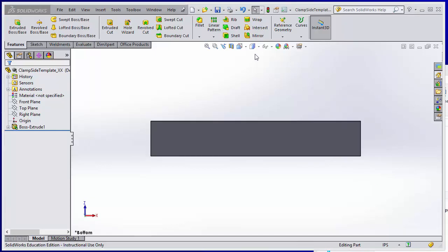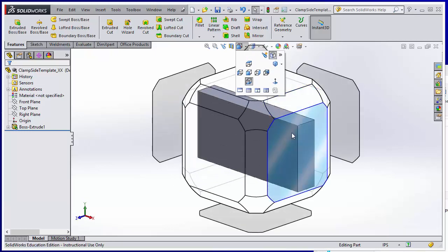You should note that it only works as the bottom if you designed on the front plane. So if I designed on the front plane with the extrusion coming out towards me, then the bottom is the shorter side of the volume itself.